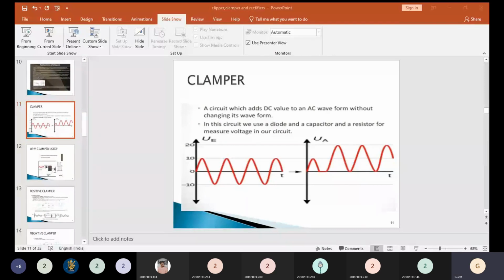The circuit shown in the figure. So this is your circuit given here. What type of circuit is it? Option A is a bridge rectifier, then ring modulator, frequency discriminator, and voltage doubler. Across the diodes, this is your diode D1 and diode D2. So it is the cathode part and the anode part. At the anode part we are taking an output, and at the cathode part we are taking an output. So what happened to your output here? The output is doubled. Okay, so definitely it is not a bridge rectifier.